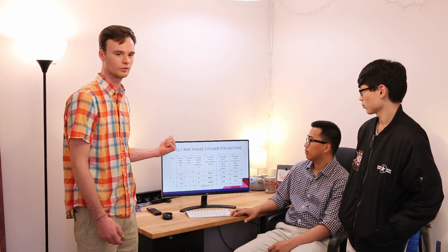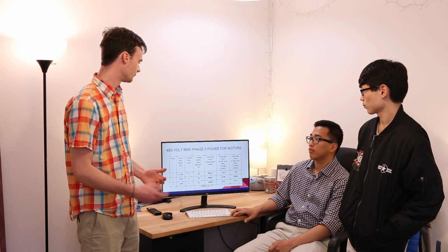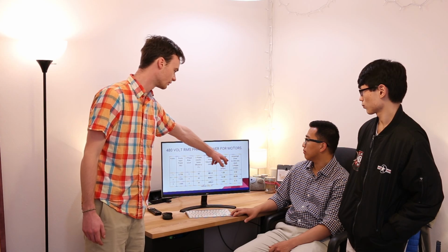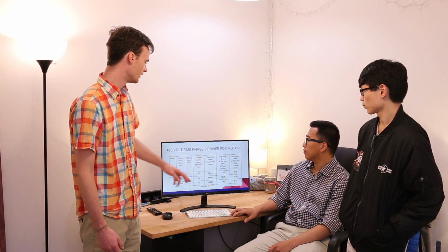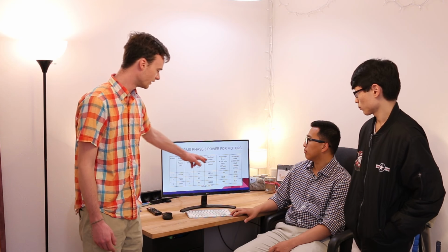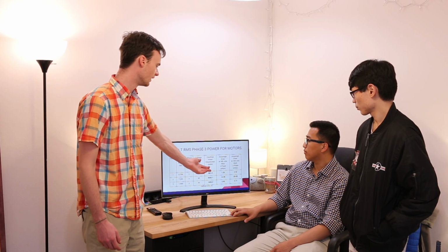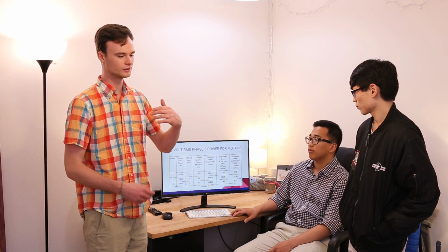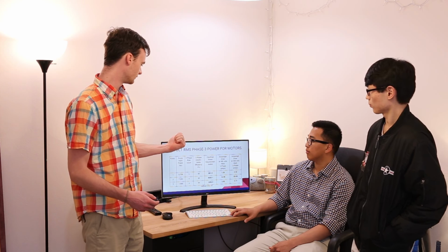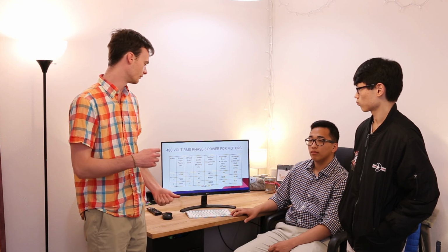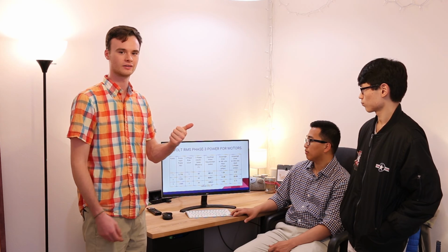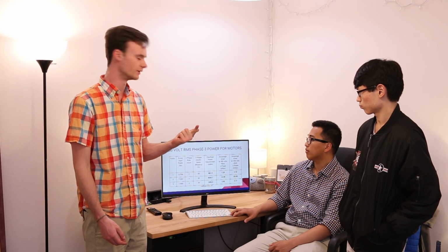Here you can see, like I said earlier, we call for 3-phase 480 power. I have also shown here 3-phase 208 volts. But as you can see, with the 480 volt 3-phase, the amperage draw is less than half. With a lower amperage draw, you can use smaller diameter wires, which are cheaper. Because you have smaller diameter wires, you can get away with less voltage loss because of the higher voltage, which saves money in cost of electricity and saves money in wiring, which is really expensive.